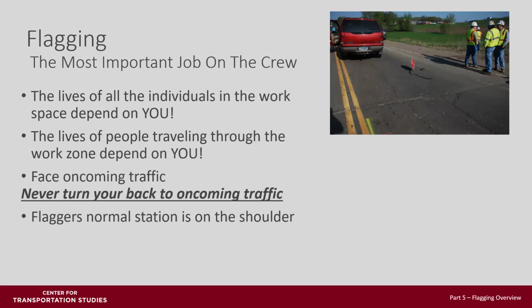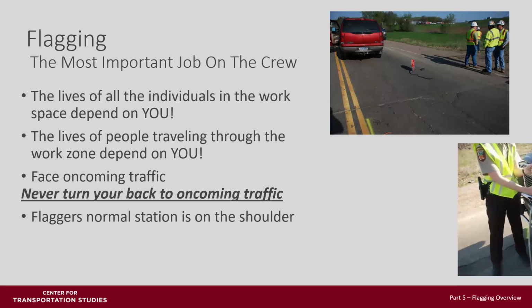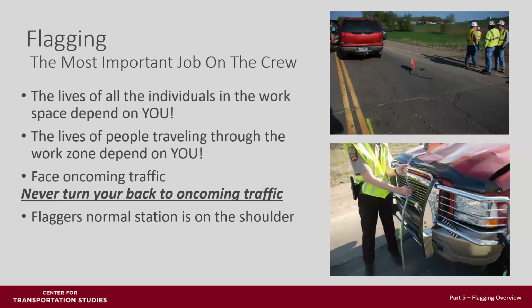I want to stress how important a flagging job is and how dangerous it can be. Always face oncoming traffic. Never turn your back to oncoming traffic. And the flagger's normal station is out of the roadway and on the shoulder.